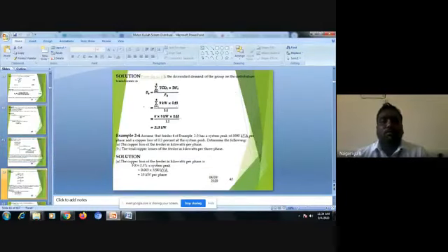So you know that diversified demand is equal to total connected demand into demand factor divided by diversity factor. Each load, the total connected load, is nothing but 9 kilowatts. Diversified demand is equal to total connected load into demand factor divided by diversity factor. Diversified demand is nothing but common demand.